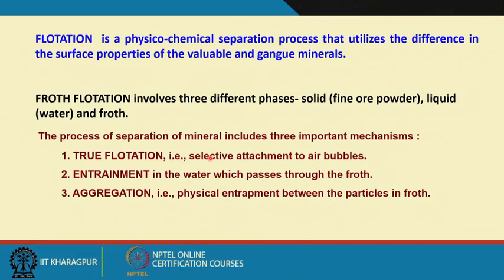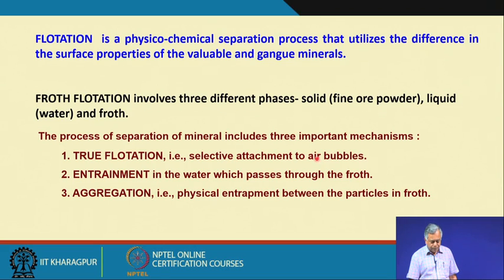When there is selective attachment to air bubbles, that is called true flotation. That means the particles which are hydrophobic will selectively get adhered to the bubble surfaces. Selectivity means the particles which are hydrophilic should not get adhered to the bubble surfaces. So only the hydrophobic particles are being lifted up by the air bubbles.